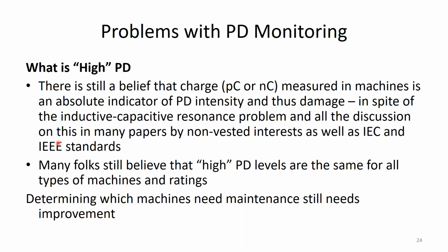That's the measurement unit that comes out. But if you read the standards, it's crystal clear that we can't use charge. As soon as you introduce inductance into the capacitive network, you're going to have natural frequencies, resonances, and stuff where you'll get completely different readings.